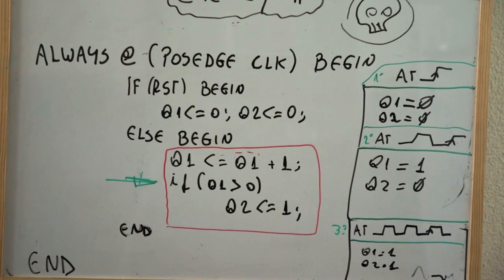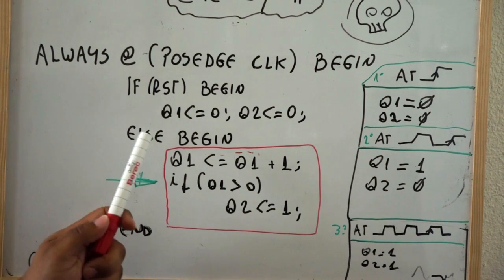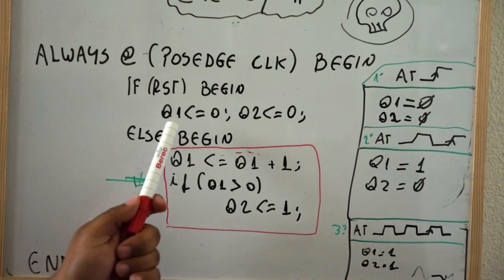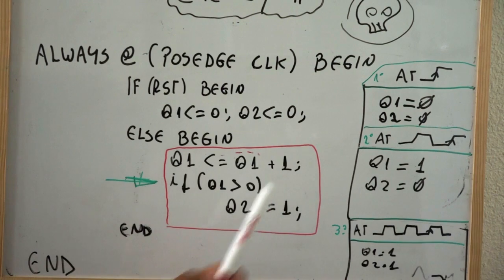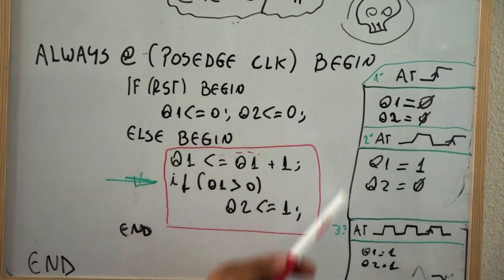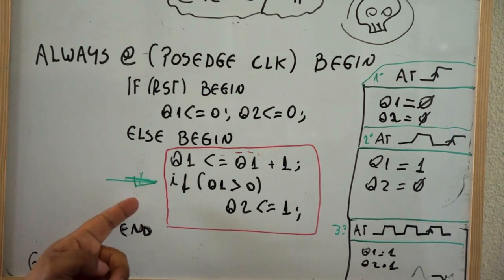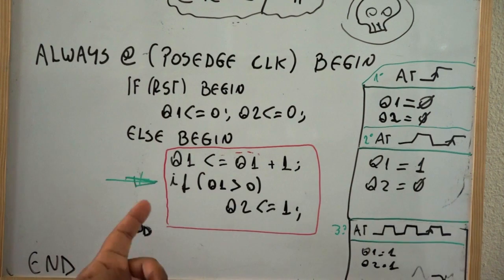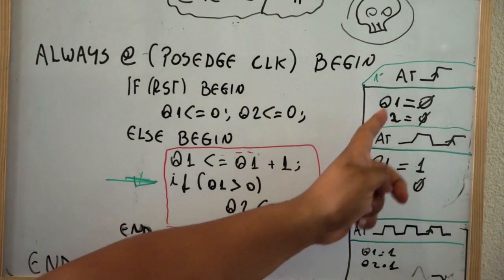Before we continue, let's take a look at a very common pattern of mistakes that you may make while developing in Verilog. Let's call this pattern the crazy if. In this code, imagine that we reset our flip-flop states to 0 beforehand, and we're going to analyze this piece of code rising clock edge by rising clock edge. So imagine that we fall into this part of the code on the first rising edge of the clock.